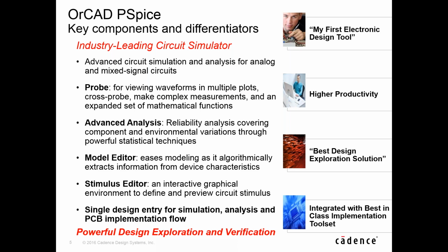In addition, we also have model editor capabilities. In other words, if you want to create any models using some predefined templates, and John will go more into depth on some of these templates, we provide modeling templates where you can go in and create MOSFETs, LEDs, magnetic models, Zener diodes. All of these components have templates provided to you so that you can take datasheet information and very quickly create a model for simulation.